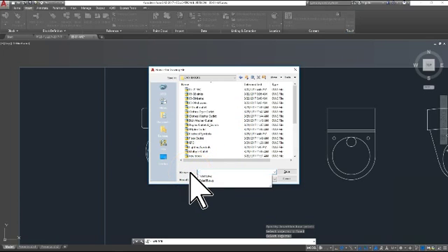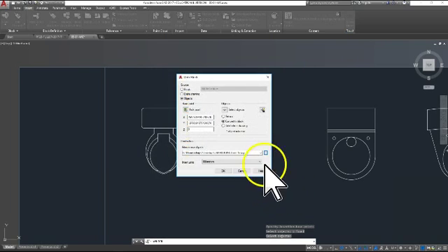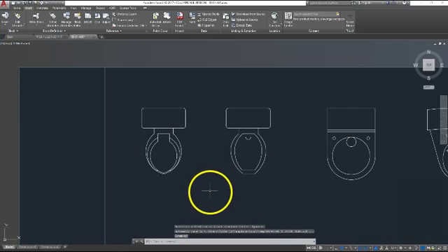Back in the Write dialog box, below the file name and path bar, it asks for Insert Units. Just leave it set to millimeters and click the OK button. You have just written your first block. The process is the same for blocks that you create on your own.